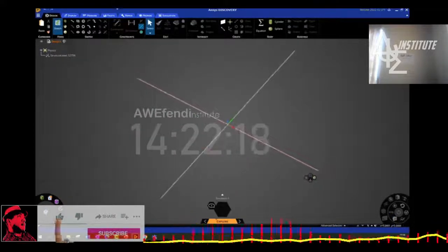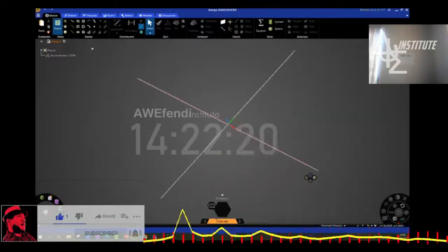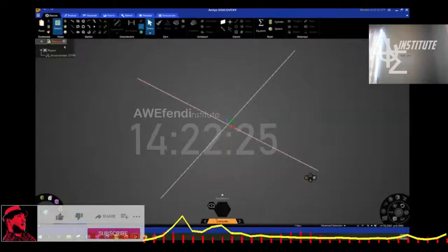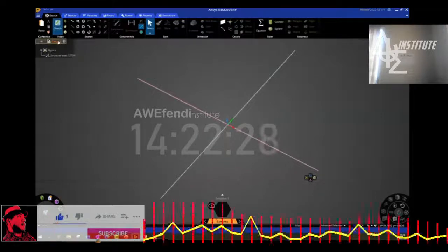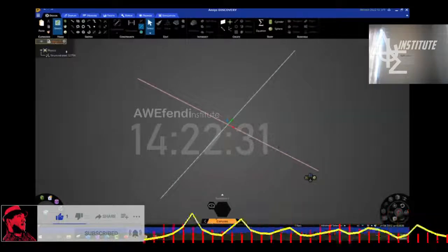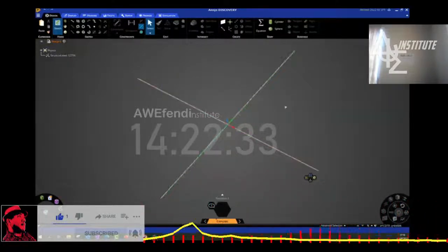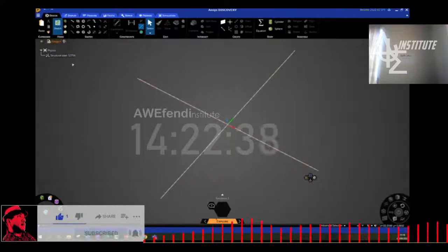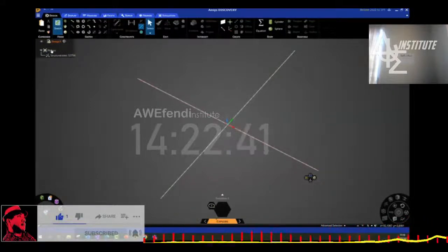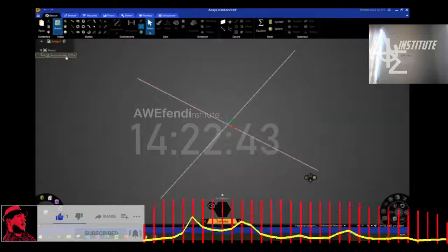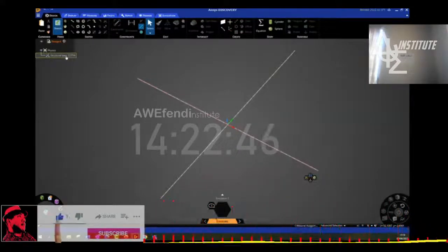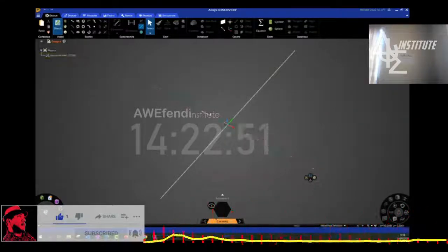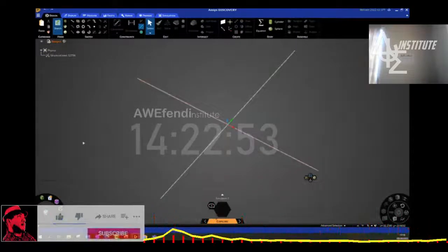So this is how the interface looks. On the left, let me point out three important areas. The first one is the model tree. This will get filled as soon as you build a model here or import your CAD models. This tree will keep growing. The next is the physics tree, where you will see the material of the model you're going to be using, as well as the boundary conditions. Here you see structural steel, which is defined as the default, but you can feel free to change that in our settings.